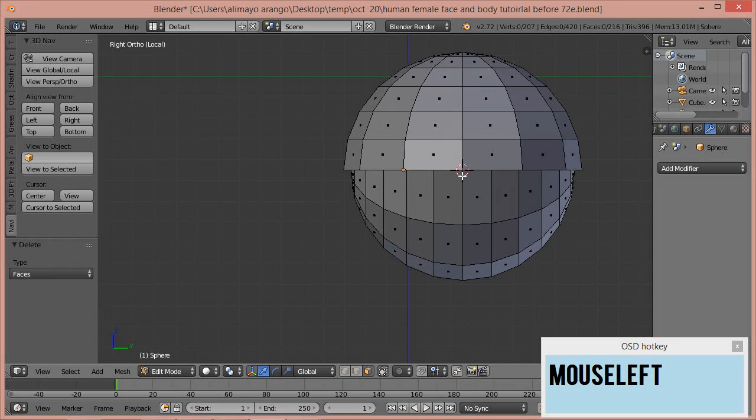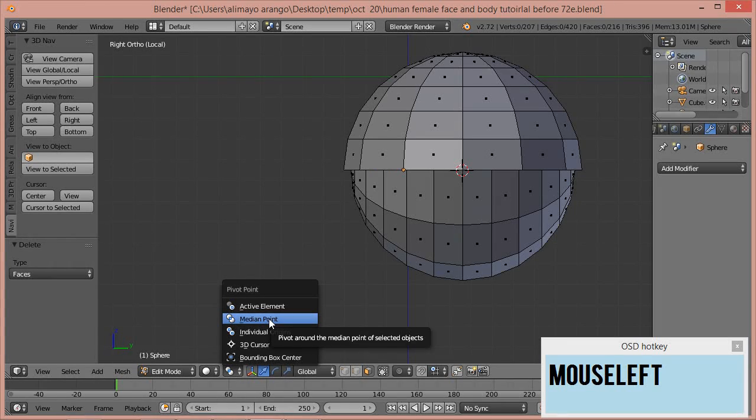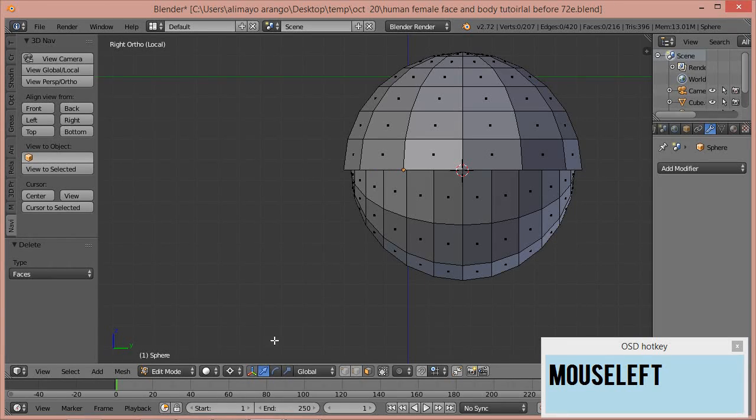If it's not there, you can click and get an approximation. You basically want your 3D cursor right here. If your 3D cursor is out here, you can right click here and it'll come back. What you want to do now with that 3D cursor there is click here. We're on Blender's default pivot point. We want to change this to 3D cursor so that this will pivot on that 3D cursor. So now, with face select on, we're going to select here.